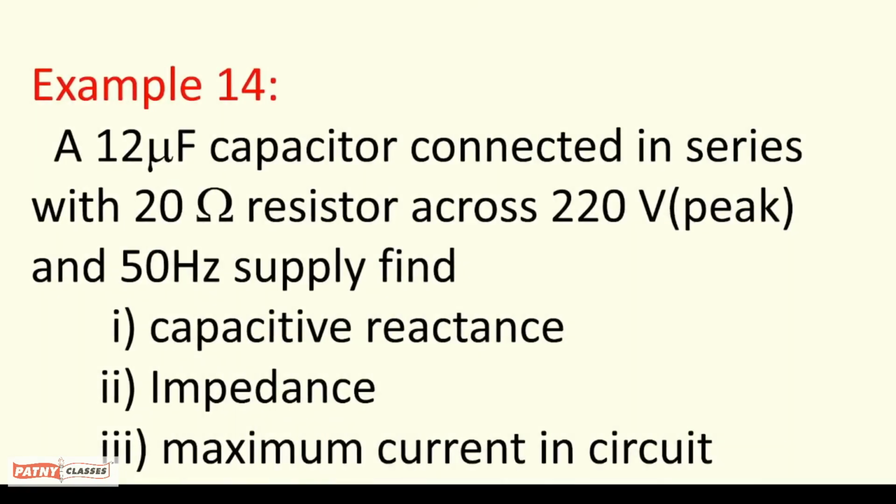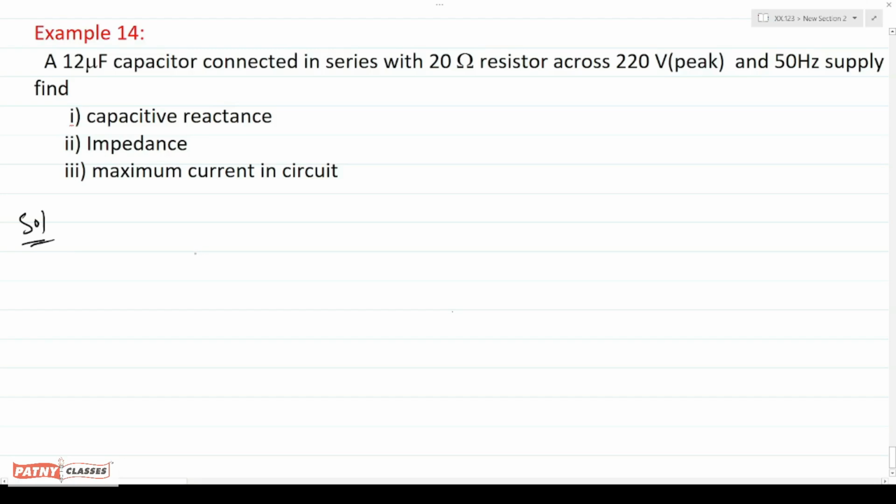A 12 microfarad capacitor connected in series with 20 ohms resistor across 220 volts peak value and 50 Hz supply. Find capacitive reactance, impedance and maximum current in the circuit. First of all, let us draw a circuit diagram.